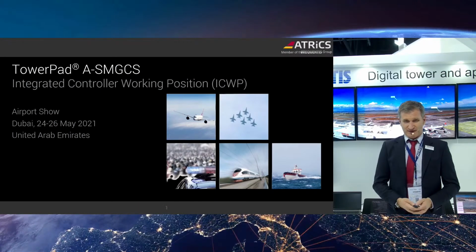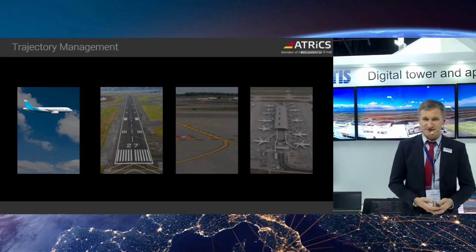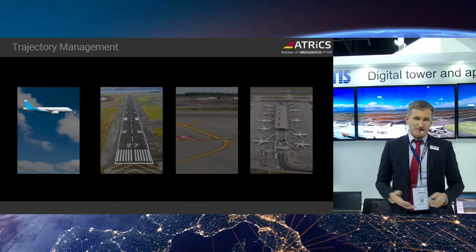I have the pleasure of presenting you the TARPAD and thereby touching A-SMGCS and integrated controller working position topics. And to first better understand what TARPAD does, you should be aware it's a trajectory management system. As you can see, at an airport we've got multiple resources: airspace, runways, taxiways and stands. And an aircraft journey across these resources is then expressed by trajectories.